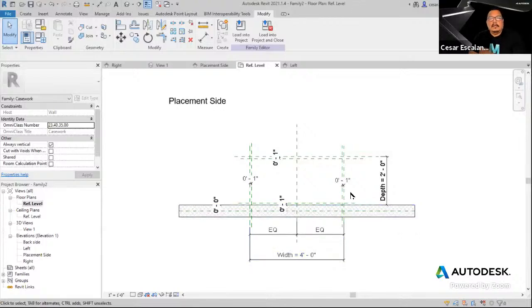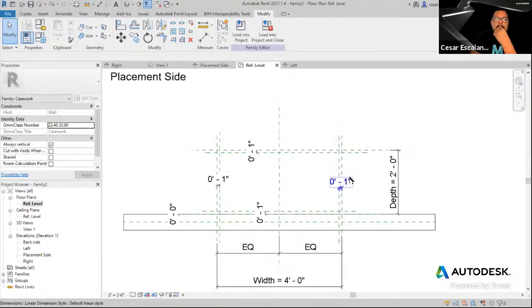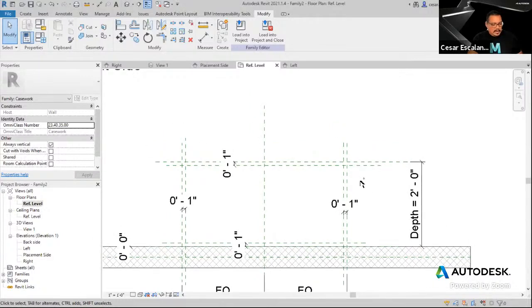So another thing I'm going to make sure that I respect is that this is the location of the doors. It is one door, this is the other door. So my solid is actually going to start from this work plane, and it's going to snap to the wall reference plane.